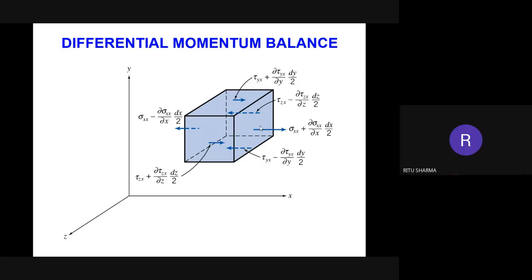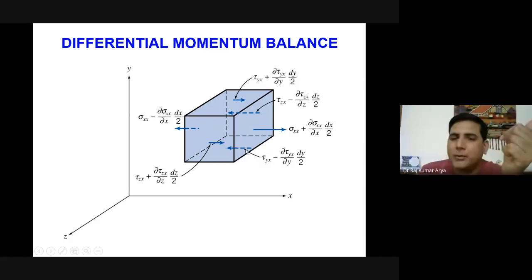Now in the bottom side you see the sign is reversed. Why is it so? Because you want to calculate everything in direction x, meaning the plus x side, so the direction is fixed at plus x. The only thing here is that the plane is minus y. So the direction is plus, the plane is minus y, and both signs do not match. Therefore this acts to the negative side. So this is the direction of the shear stress on the bottom plane.